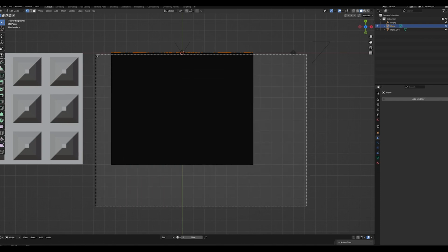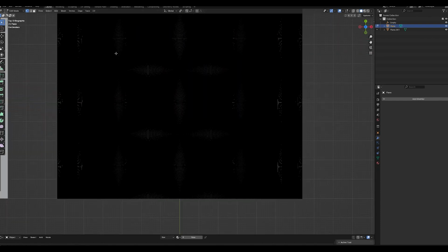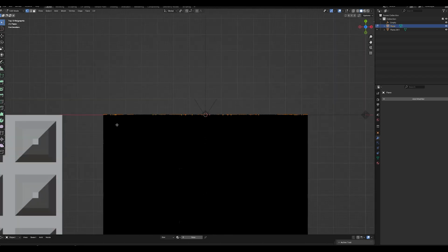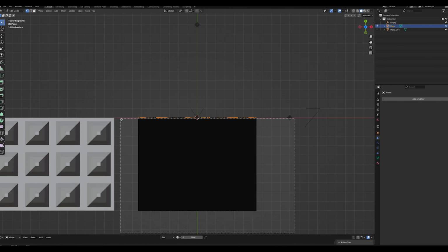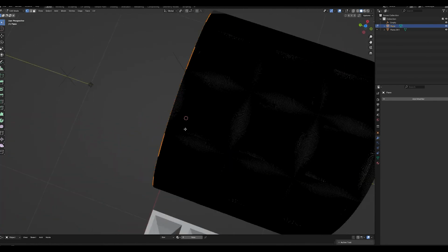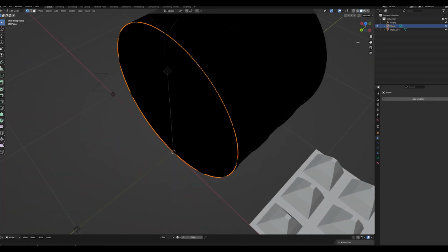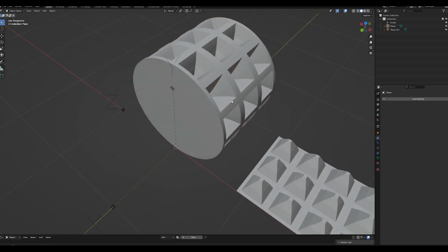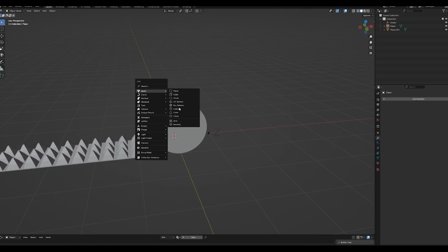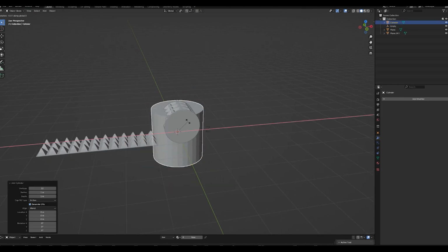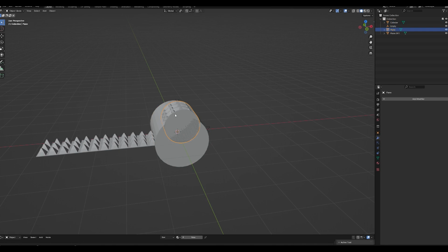I'm going to do the other side, and in X-ray mode, deselect everything else, and then realize you unselected too many of the good vertices, so you have to undo that, and then deselect again, hoping you get it right that time, and then press F to face, and you should be left with a nice solid model. Another step to add here, I would select all of the vertices and recalculate the outside normals, because some programs like 3D printing programs will have a hard time with that if you don't.